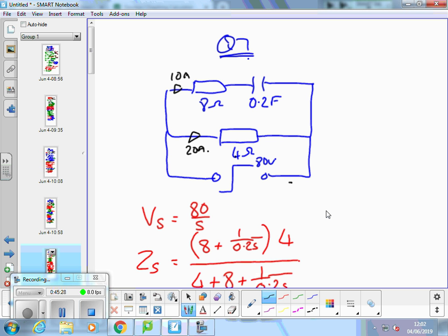So if you understand the underlying principles of capacitor charging and discharging, and inductor charging and discharging, you can make an estimated guess as to what the shape of the graph looks like and what the results might be before you even start. Think about what happens at the instant it turns on, what the expected conditions of the components are, and what happens after the transient period is finished. A capacitor will be like an open circuit after the transient period, fully charged up, and an inductor will act like a short circuit after the transient period.